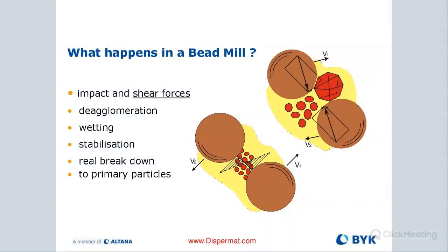So what actually happens in a bead mill? As you know, we use media that is either zirconia based. Some people use glass, which we don't recommend for various reasons. We'll cover that in a minute here. But these beads are perfectly round under the microscope, or at least they should be. If they are not, then maybe you need to look for a different supplier, because it's really important that you have high quality zirconium beads, either cerium stabilized or yttrium treated. The ones that are white and then the other ones are brownish in color. But it is really important that they are perfectly spherical.